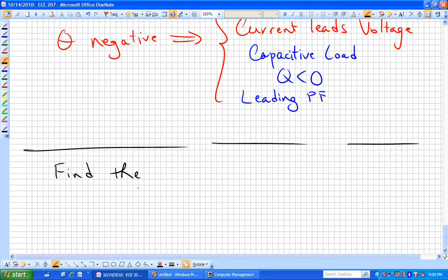Well, you might say, you know what? I've had 207. I know how to get that angle down. So you put in some capacitor banks to supplement or augment your motors, and you now try to lower that angle to maybe make your power factor 0.9 instead of 0.7. And that's what we'll do after I give you this class participation problem. But did that answer your question?